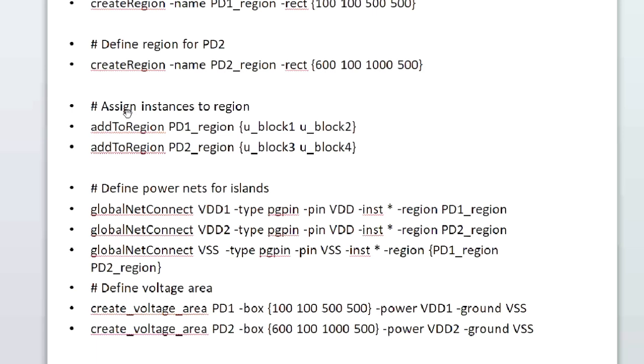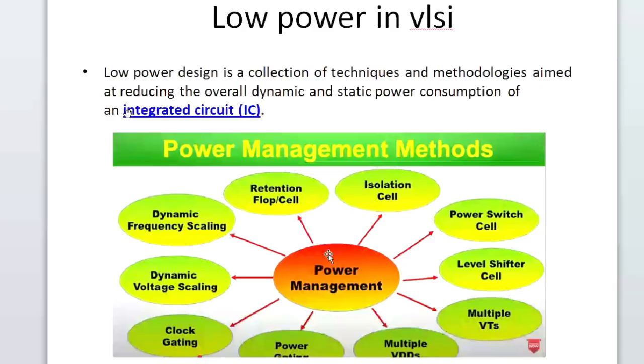And let's say here, low. These are the low power cells which are controlled by the PMU. PMU is nothing but the power management unit for all those submodules. You can see the power switch, multi-VDD, and it controls them because it has the control enable signal for each and every cell in the design. Let's say for a power switch it has an enable pin, and likewise for level shifter and isolation. Through that enable pin it controls the design to interrupt the power.